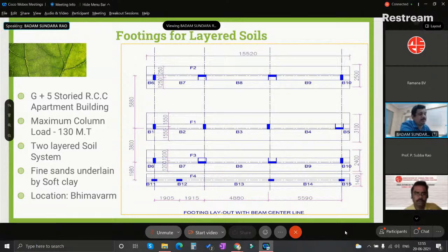In the case where the sand layer is in contact with the soils, we have to provide a sand layer depth of not less than 300 mm, such that this will act as a drainage path for the pressure dissipation, and minimize the consolidation settlements which go much beyond the total settlements prescribed by the code. That is, there is a correction factor lambda in IS 8009. You can refer to those values. Once you have a better drainage system, the practical consolidation settlement that occurs is much lower than what we anticipated during the analysis or computation stage.